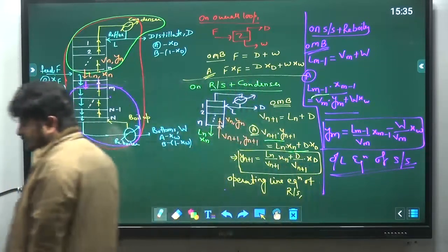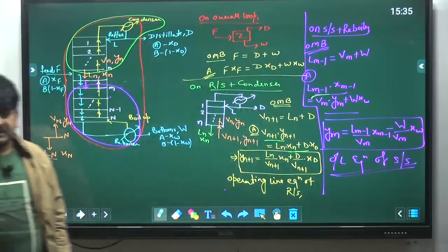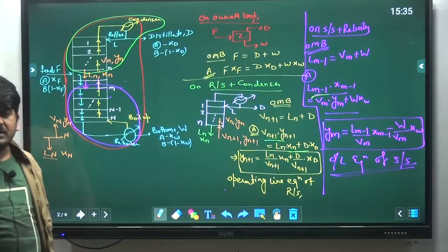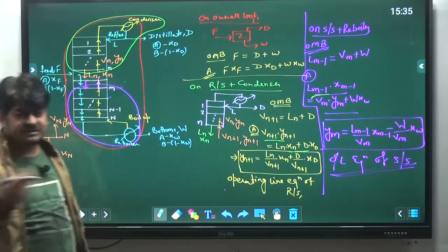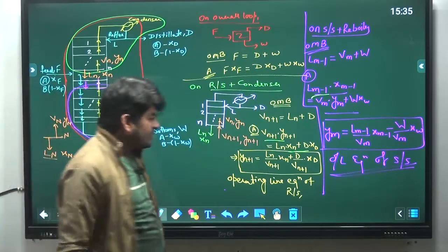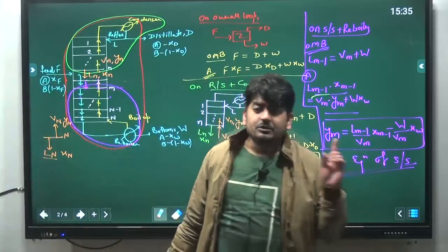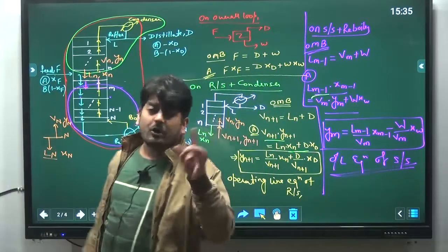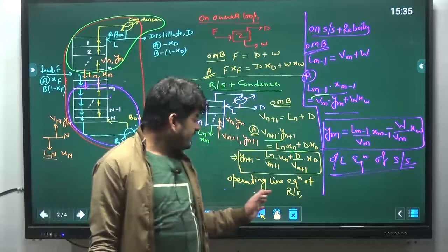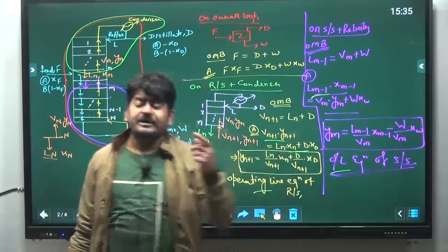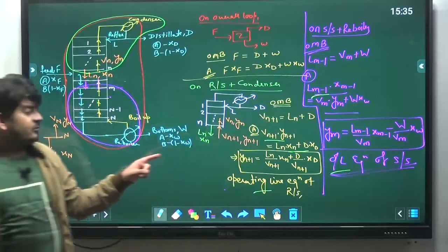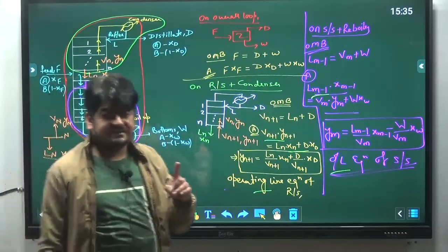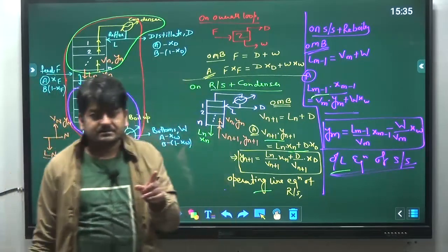So if this is the actual amount, not the rate, you can say moles. But since these are the flow rates, these are mole per second. Okay. What about the operating line equations here? Remember these operating line equations are dimensionless but not unitless.